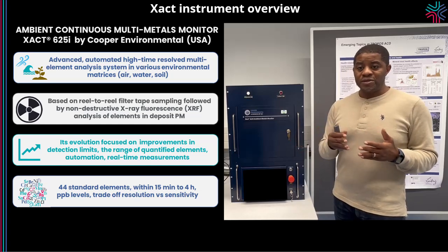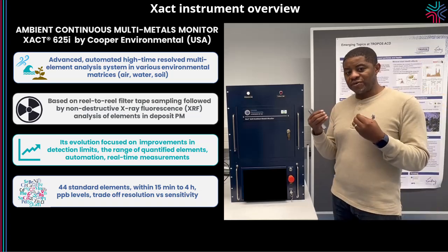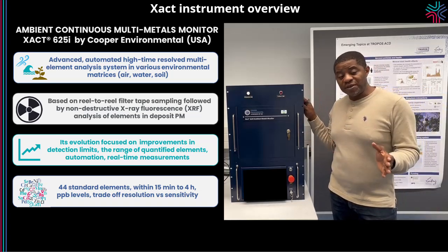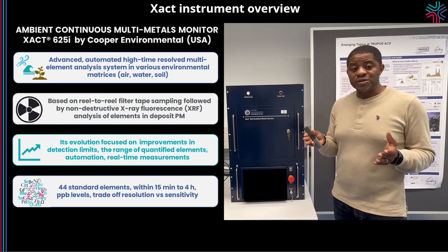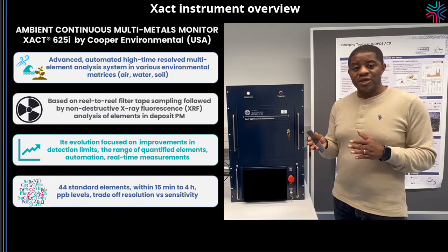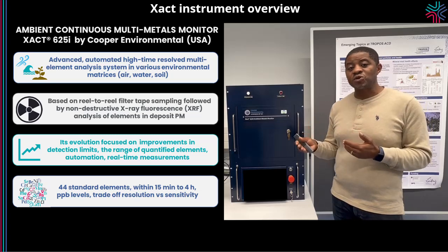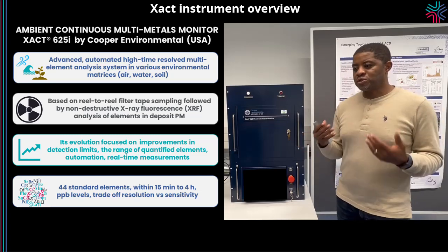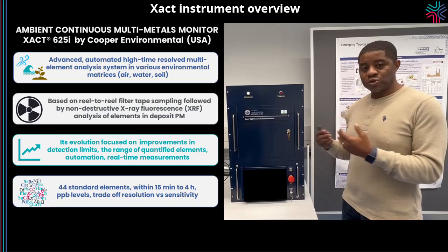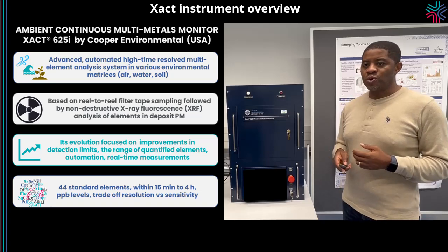But when you're in the field, you're always thinking about the time resolution, so you have to get information within every time span. The XACT can measure from 15 minutes to 4 hours time resolution, but there is a trade-off between resolution and sensitivity. If you go for a quicker time frame like 15 minutes, the sensitivity is not as good as if you go for 4 hours. Most environmental protection agencies go between 1 hour and 2 hours. And most often in our campaigns and in most of the studies we do, we also go for 2 hours.